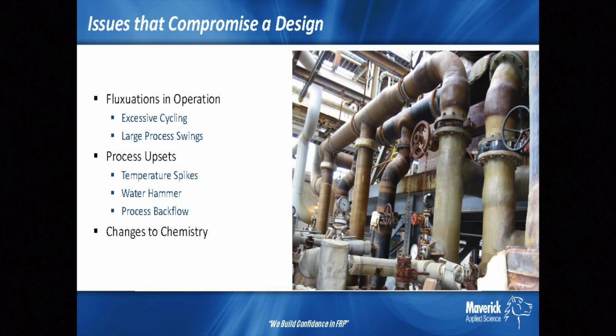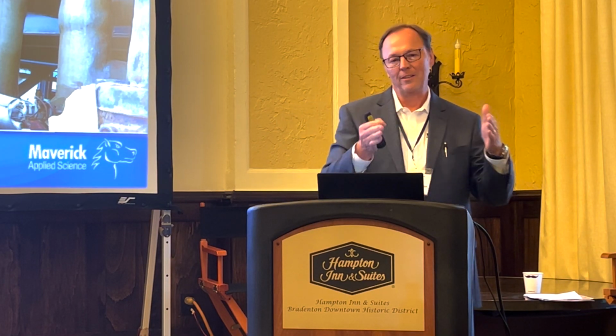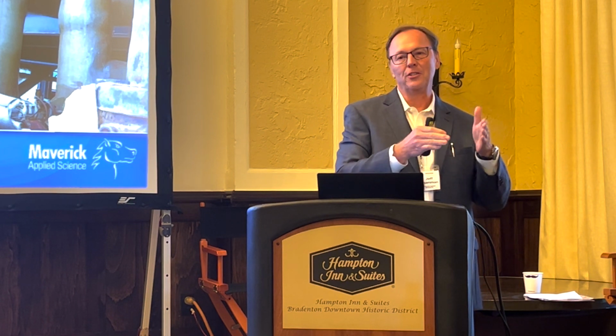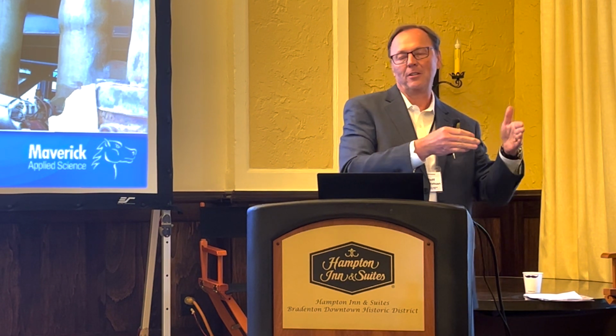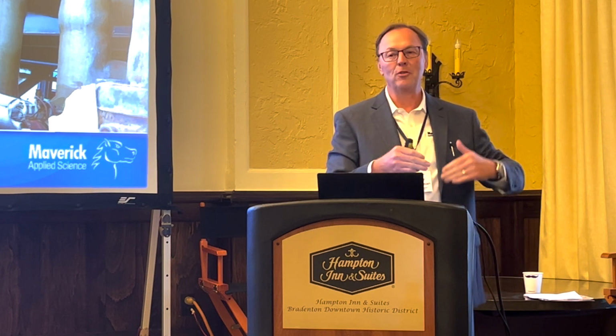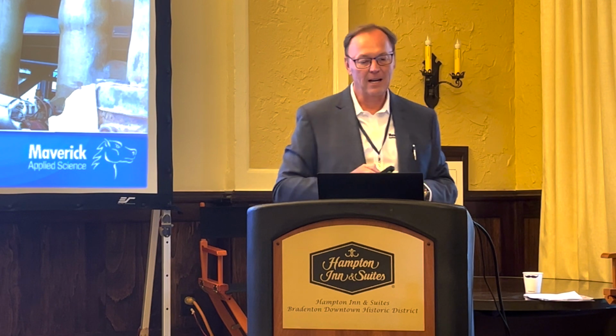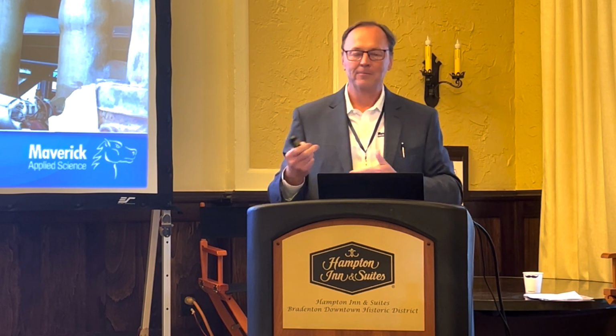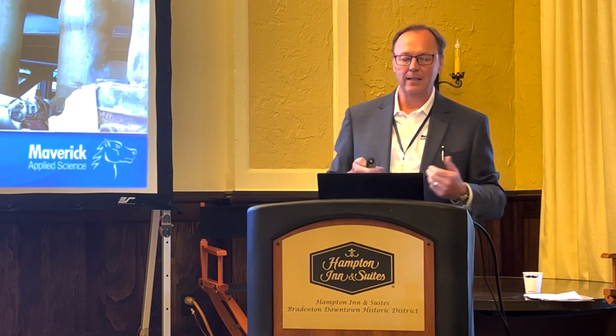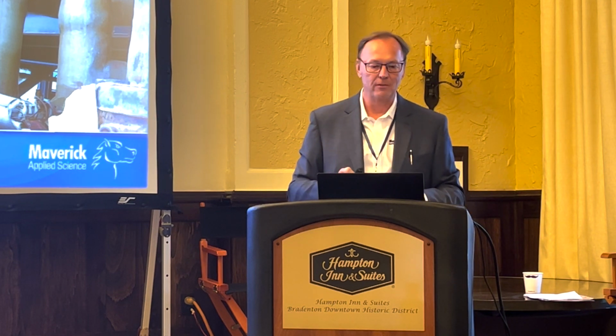Changes in the chemistry we see, kind of like what they were talking about before with sulfuric acid. At 93 it works great. Well, we're pushing the envelope a little bit more, so we changed the chemistry, and now we're running a little bit higher. This material is good for this process up to this concentration, but maybe it's good for 32%, but not 37%, something like that. That kind of thing happens. These things happen during operation, and they do challenge the material.